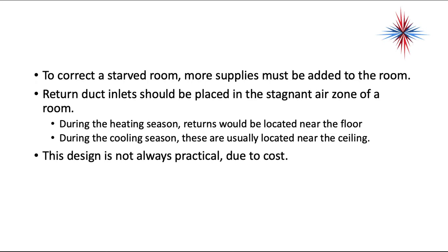Return duct inlets should be placed in a stagnant air zone of a room. During the heating season, returns would be located near the floor. Remember, cold air falls. We want to pull the cold air out of the room. During cooling seasons, these are usually located near the ceiling.